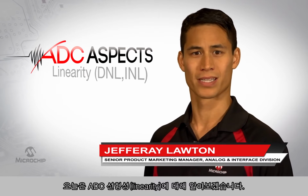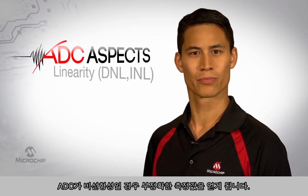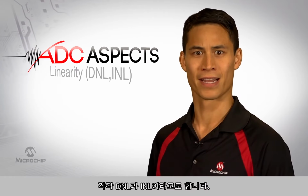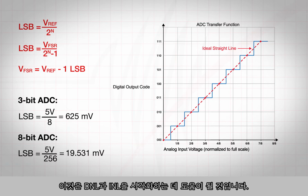In this episode, we'll discuss ADC Linearity. When an ADC is nonlinear, it brings imprecision in measurements. Two important parameters are the differential and integral nonlinearity, or DNL and INL. In the first episode of ADC Aspects, we introduced the ideal transfer function and LSB. This will help us visualize DNL and INL.